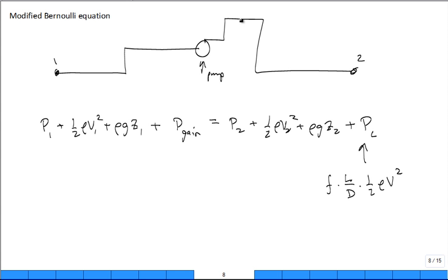Now you say, I have this section of pipe here, section 1, then section 2, then section 3, then 4 and 5 and 6 and 7, etc. Each section could have its separate friction factor. Now, if each section has the same diameter, same type of pipe, same relative roughness, same mass flow rate, well, they're not going to have a different friction factor.